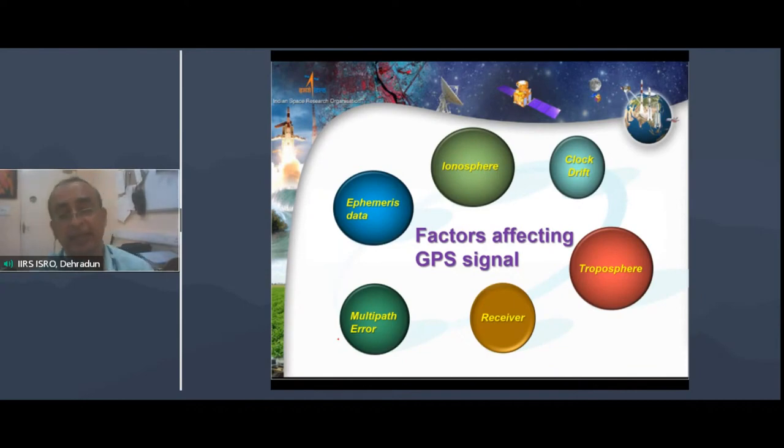So I've also talked about GPS based errors which are present in these systems. The error can be due to satellite orbital parameters, multipath error, ionospheric error due to ionospheric layer, clock drift, error in the clock of the satellite, tropospheric layer, which is basically water vapor and the dust content, and charged particles in the ionosphere. And at the receiver end, receiver error, how the receiver is set up, multipath problem, receiver noise, and so forth.